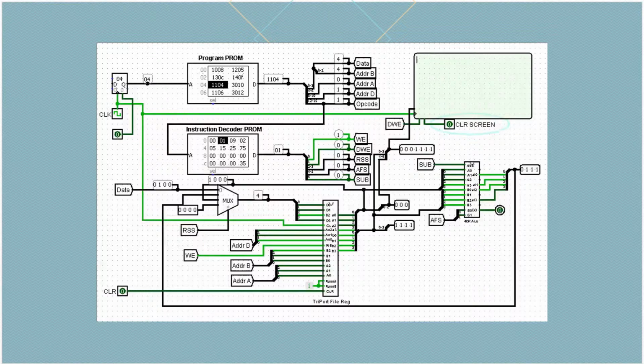This is how the program works at 8 Hertz. At the end of this first phase, we'll do a subtraction, which is done by taking the number to be subtracted, XORing it, and adding a 1 to it, and that being added to the other number, which is a 4, and so you come out with a 1. In phase 2, we use the adder subtractor and actually use the subtract function, which performs the same function.